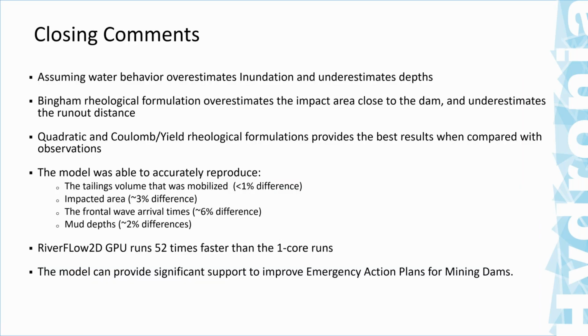So just some closing remarks here. As I said, this wasn't an actual project. It was an exercise to assess how the model was able to represent a real event. So the lessons learned that we got from this is that assuming water behavior greatly overestimates inundation and underestimates depth. So it shouldn't be used as a proxy for tailings dam breaks.